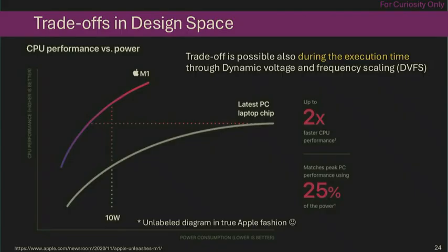It happens all the time. When you open a new app or a new website, your processor is just running at a higher clock frequency for a few seconds before coming back to the idling frequency. And you can get some power saving when the processor is running at a lower frequency using DVFS.